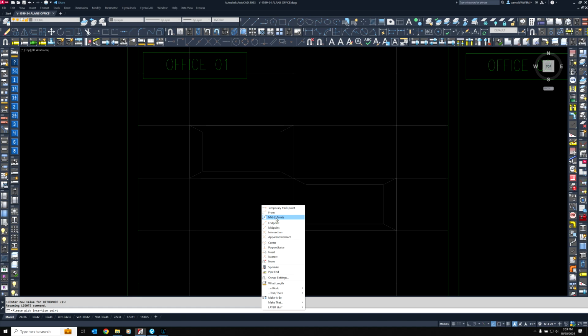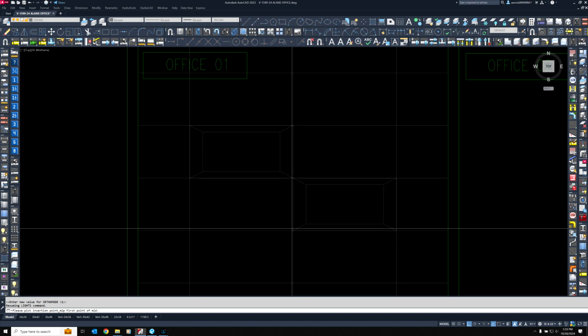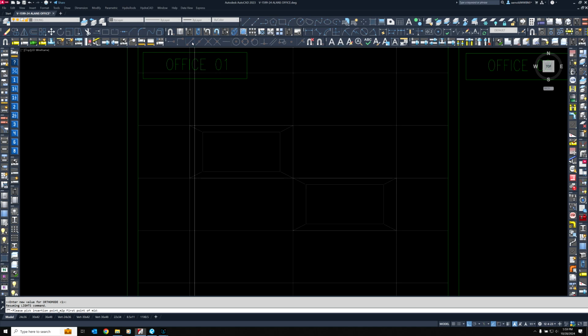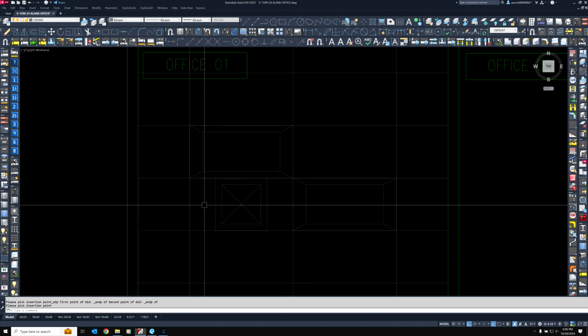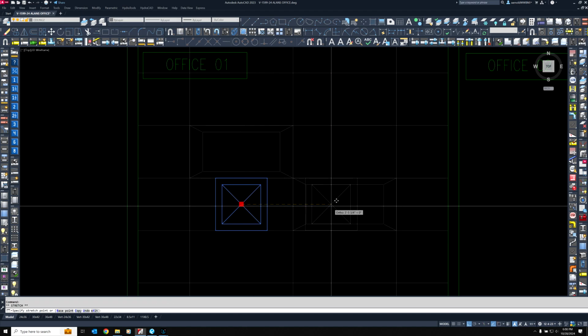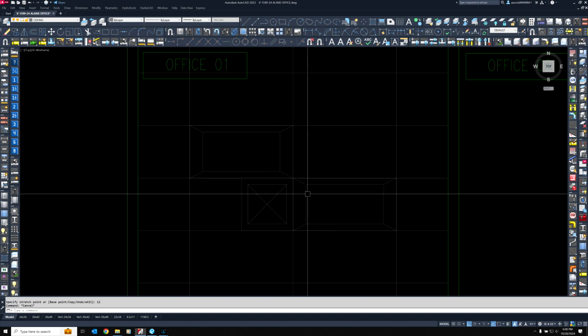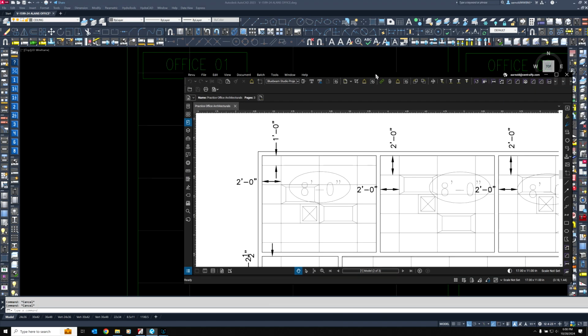We're going to use it anyway just to show you what it does. So left click on mid 2 points, and then we're going to pick the intersection or the endpoint of the lights, and it's going to drop the diffuser centered between those 2 points. Hit enter. We're out of that command. Now let's just grab this, and we're going to move it 12 inches, and now everything lines up just the way it's meant to from our PDF.